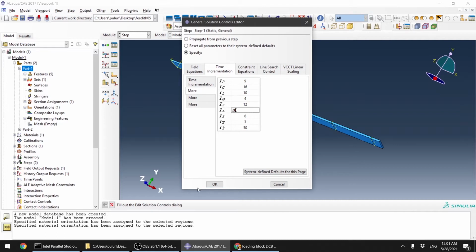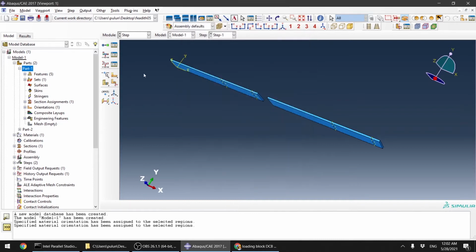With the default it would be an error after 5 cuts, but here it will try 6, 7, until 20 cutbacks. So it's more difficult to get an error message. Abaqus will try harder, harder, and harder to find the solution.